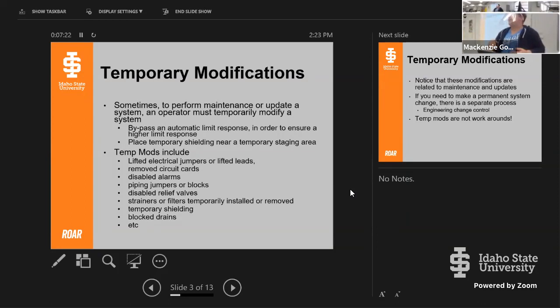But the problem is that when your rad protection engineers and radiation safety techs determine where you have to have shielding, you can't move that shielding. So if they have to put in some sort of temporary shielding, all of the operators and personnel in the facility need to know, is this permanent shielding that we have to test and make sure it doesn't have cracks that are allowing some streaming dose through it? Or is this just here temporarily for this particular job? It's been assembled correctly today, and I can verify that before I go do this work, right? What our shielding is for is important. And so we need to know if it's temporary or permanent.